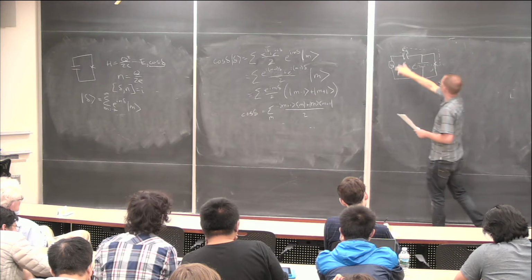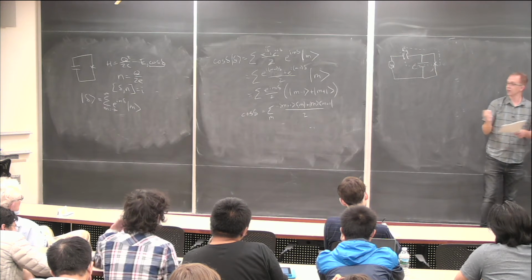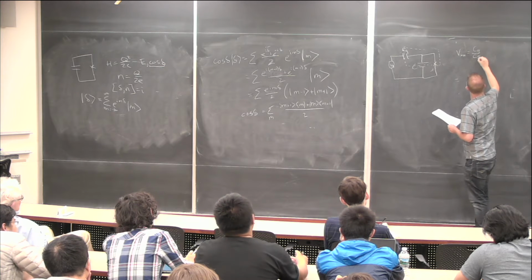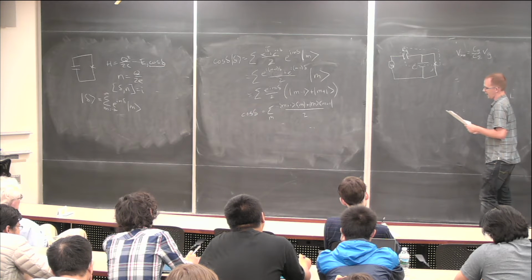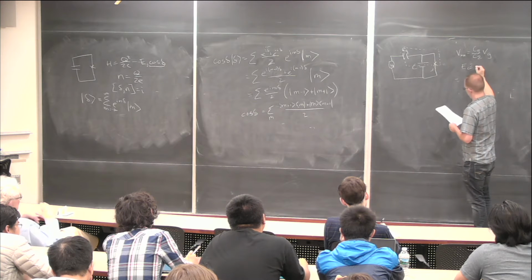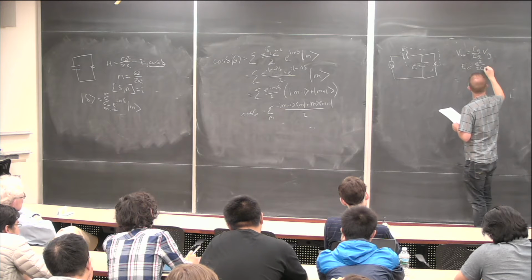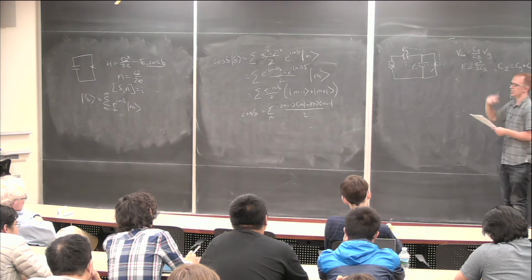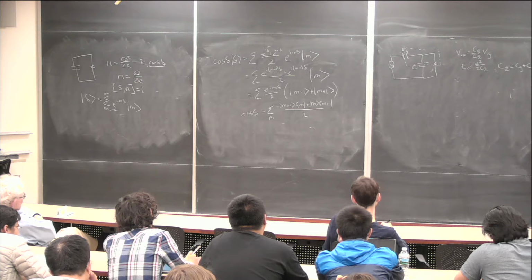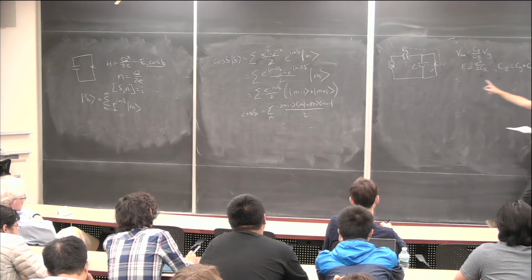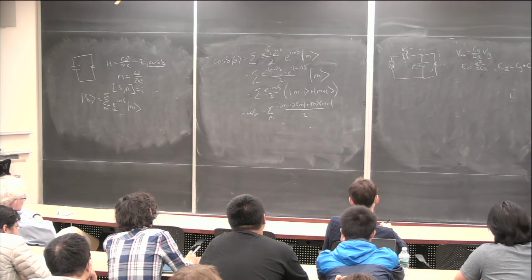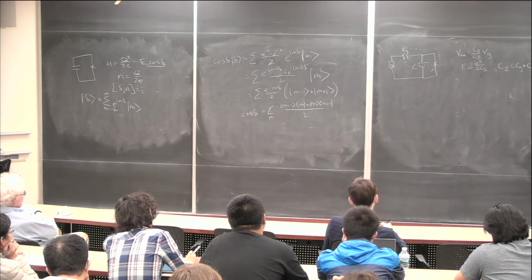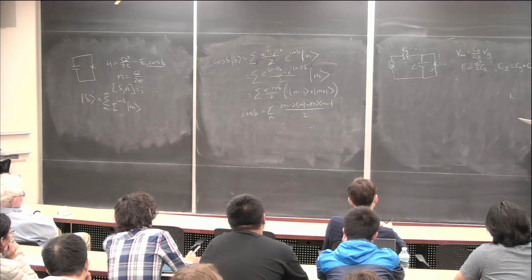And we can then bias this box with a gate voltage, right? And so the voltage on this box is C_G over C_sum times V_G. That's just a voltage divider. We are going to define the charging energy to be e squared over 2C_sum, where C_sum is the total capacitance of the island, so it's C_G plus C. So e squared over 2C_sum is the charging energy of a single electron tunneling onto the box. Note, it's defined historically in terms of the charging energy of a single electron and not a single Cooper pair. So we'll get some 2e squares popping up.